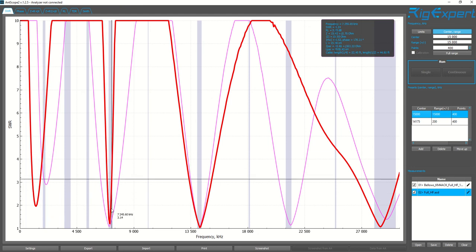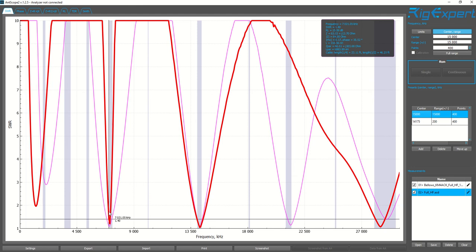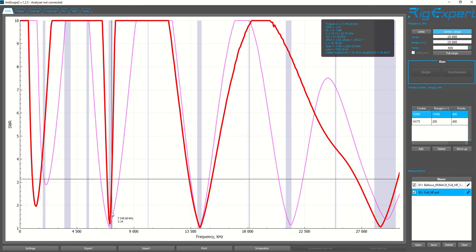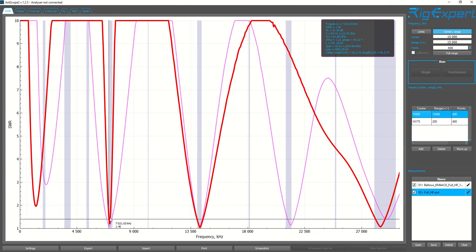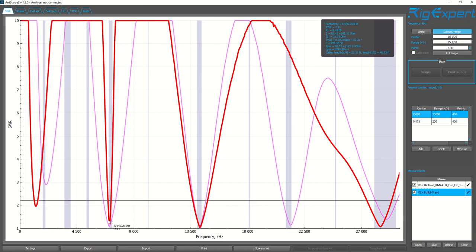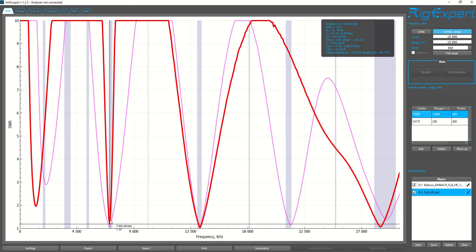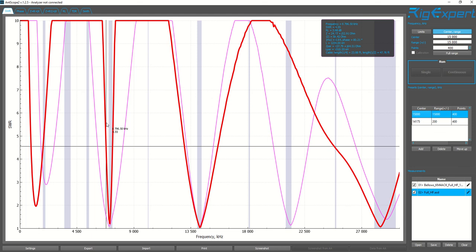And you can see here that on 40, the bandwidth of the PAR end-fed is very narrow compared to the KM4ACK antenna. The main reason is that the LNR Precision PAR end-fed antenna uses a coil in order to give you 40 and still keep the radiating element short. And so the coil really tightens up the bandwidth there.